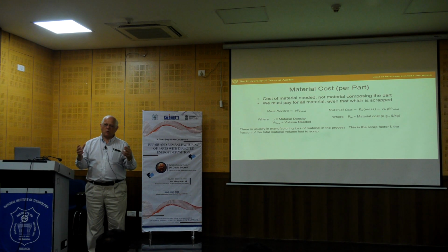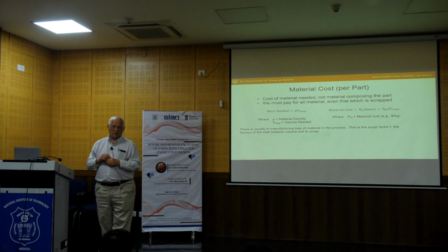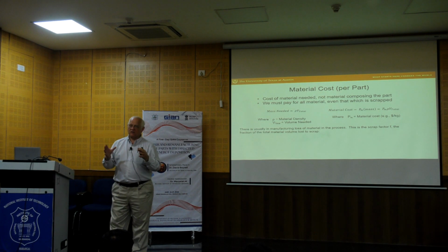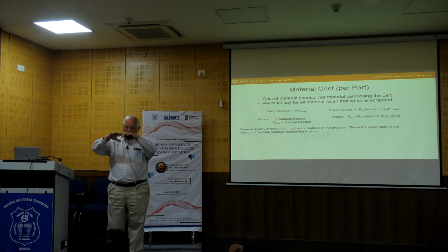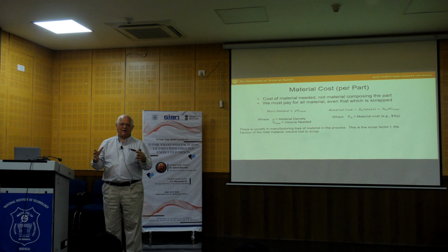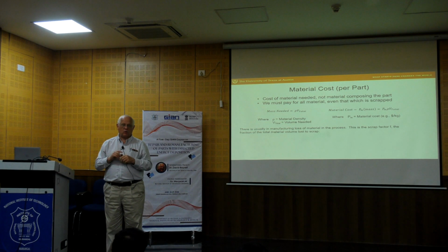Maybe we can fill about 20% of the chamber up with part, and then the rest is just feedstock, same with powder bed. So what that means is that if I'm going to charge fully the machine to do a full chamber build in PEEK material, the material cost is about $40,000, or at least it was at one point. It may still be.